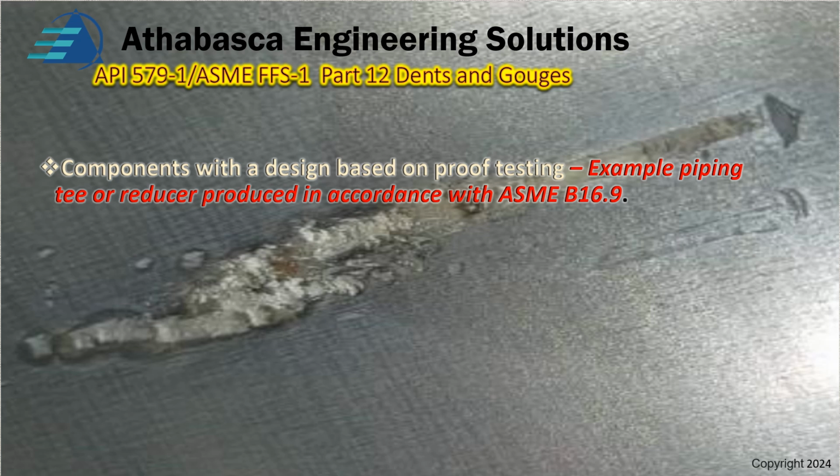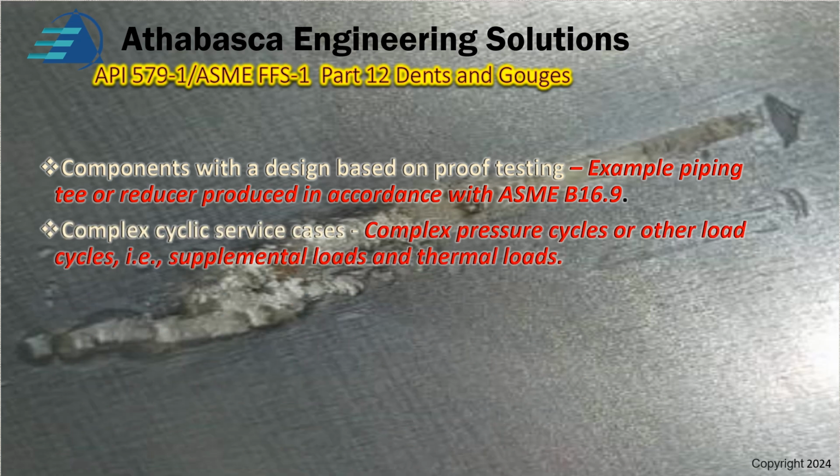Continued. Components with a design based upon proof testing, for example piping tees and reducers produced in accordance with 16.9, require more detailed analysis.